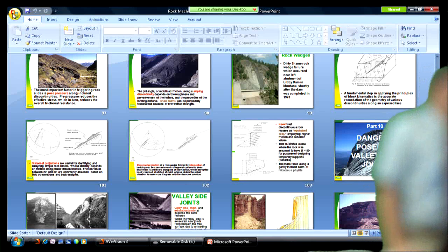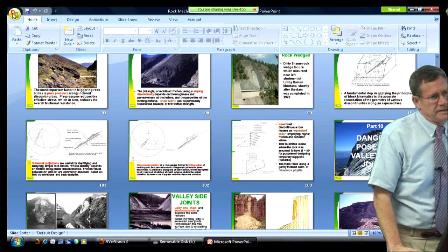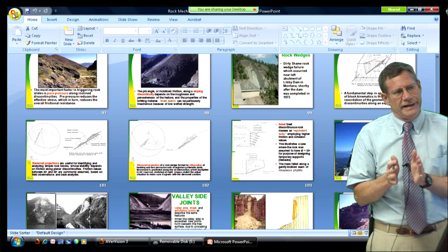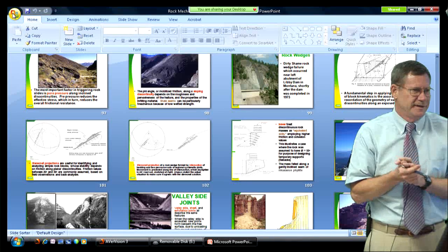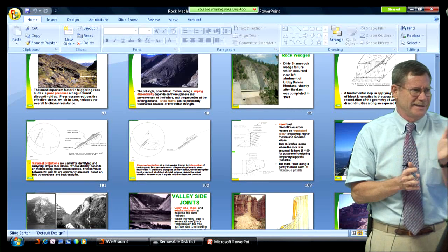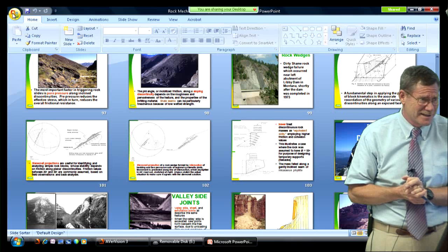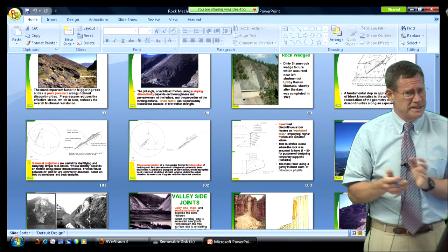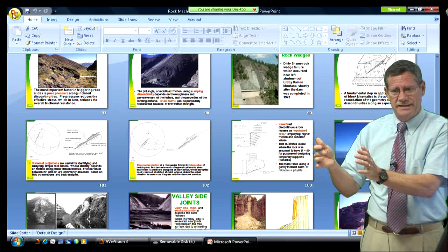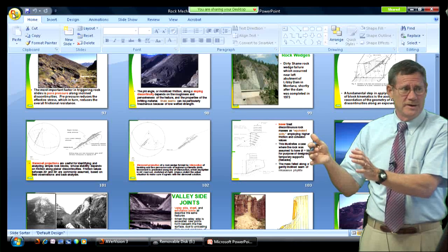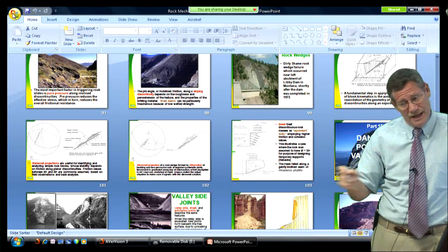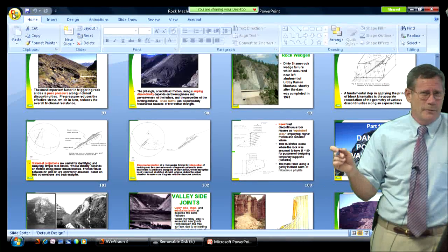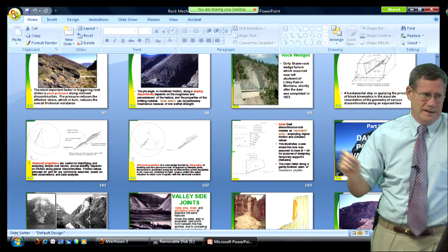It's really tough to model, but what it's telling you is you do have a cyclic loading every day, where there's an opening and a closing and an opening and a closing. And I showed you the impact of load cycling on the tensile strength of rock. It's dramatic. When we say the tensile strength of the rock is such and such, that's for one cycle of loading. What's the tensile strength for 2,000 cycles of loading? The answer is something a lot lower. So rock is very weak in induced tension cyclic loading.